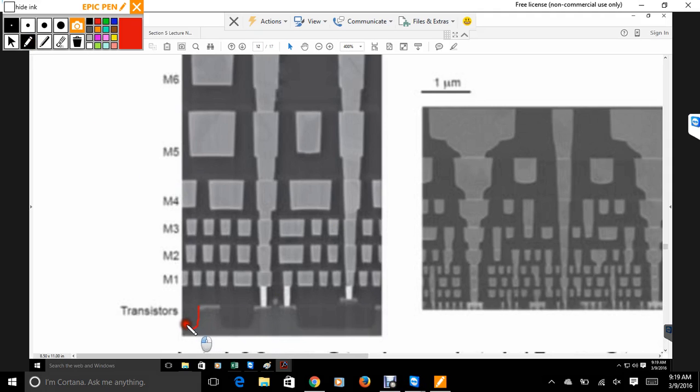Okay, so here you got the actual transistor design. Can you see this right here? You actually have your wells, and they're connecting to the gate. And then you're actually having communication going on here. So you have all these different wires going in between. So you see this is the 90 nanometer here on the left, and this is 45 on the right. So you see how the metal 1 in the actual technology is much smaller? And you're using 8 different metals to try to communicate. You're trying to create dielectric space between each one of these. So the whole goal here is to try to prevent these from having too much of a capacitive effect. So you want the transistors to actually work.